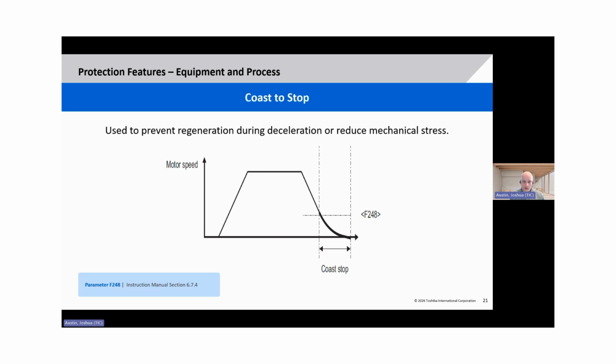So there are multiple ways to achieve this. It can be done by programming one parameter to coast after a certain frequency, or you can use your digital inputs or communication registers to initiate that coast to stop as well.